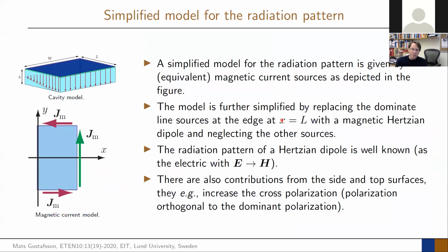And that is the simplified part of the radiation. Of course we have very strong electric fields on this side, so very strong here. And that means that we can model these with a magnetic current that goes there. So here you have your JM. And here, very weak fields and very weak fields there. So everything is dominated by this field that sits along this width side that dominates the radiation.